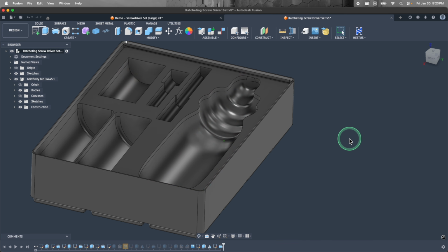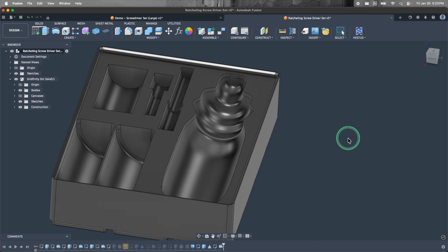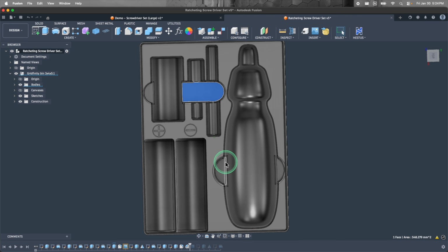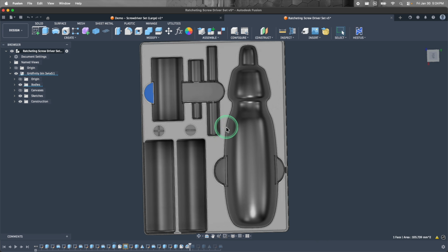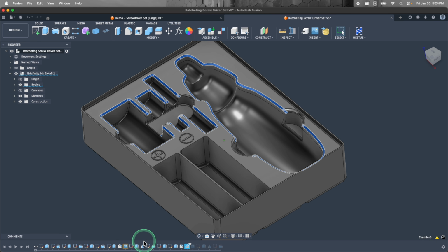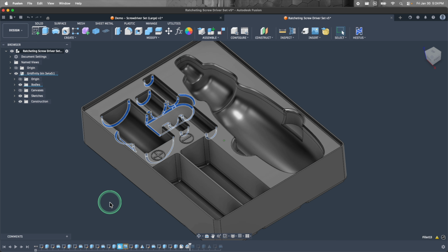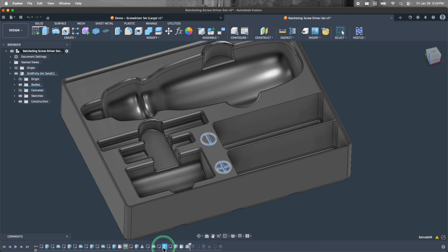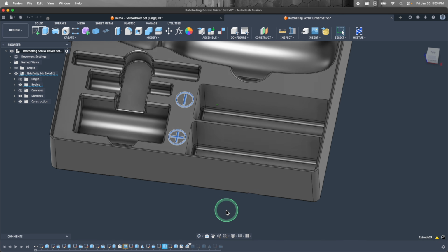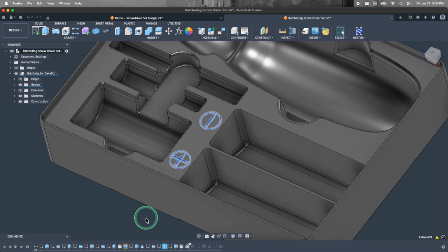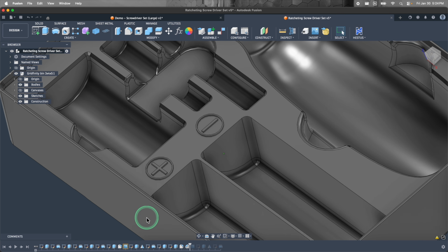Just like that, we've got a couple of methods to make our custom designed cutouts in Fusion. My parting wisdom here as well: make sure to incorporate some slots for your parts as desired to give you an easy way to pull your parts out. And it's a really nice last step to perform some beautification by adding in some fillets and chamfers all around your part. You can also add in things like text or symbols simply by throwing in some additional extrudes if having some identification for your parts is desired.